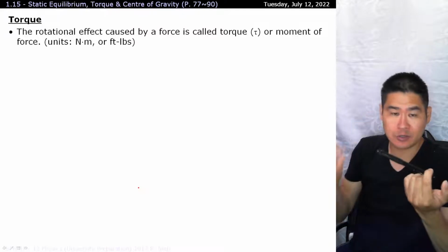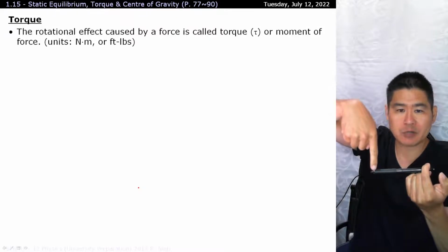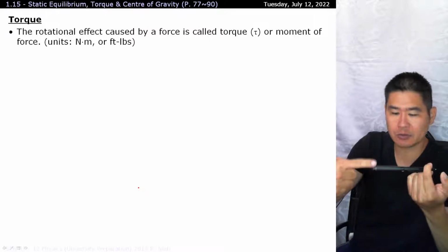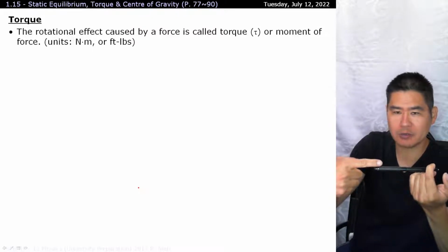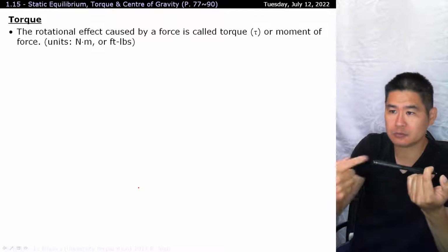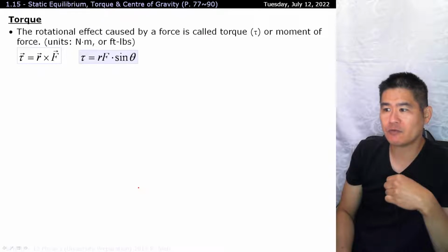And there's actually a trig function that operates that way as well. When you're exactly at 90 degrees, you're at 100% efficiency. And when you're at 0 degrees or 180, you're down to 0. And that's sine. So sine of 90 equals 1. Sine of 0 equals 0. Okay, or sine of 180 also equals 0. And that's why that's incorporated into the formula as well.